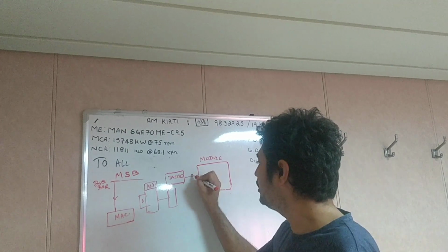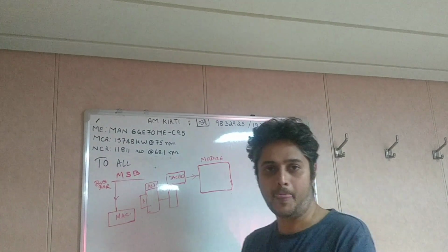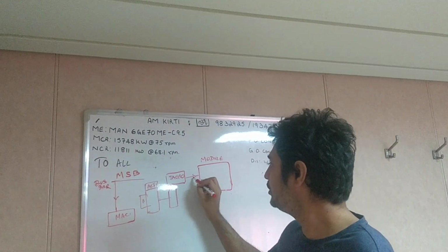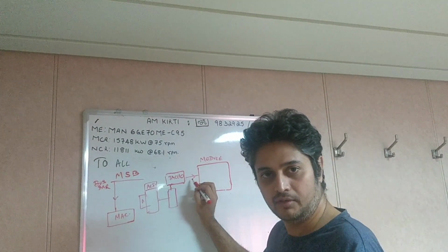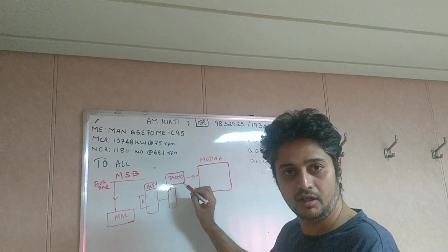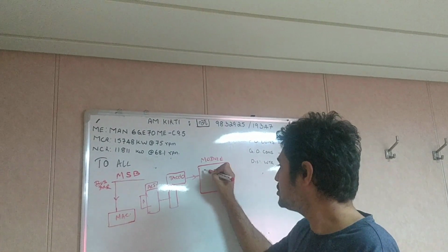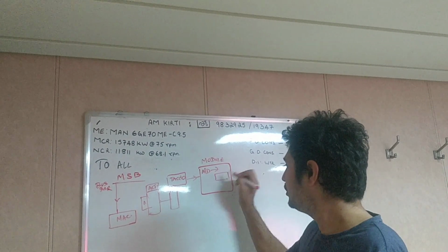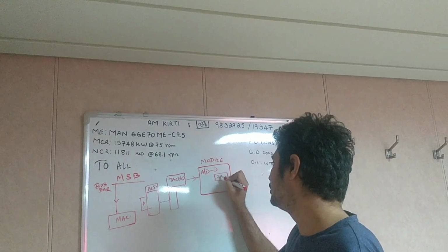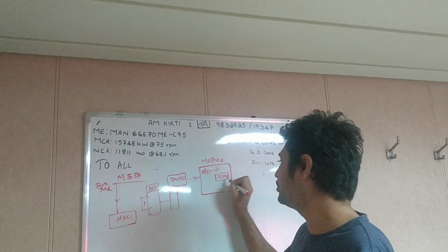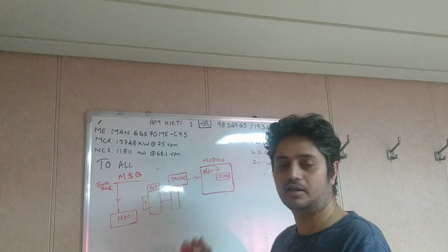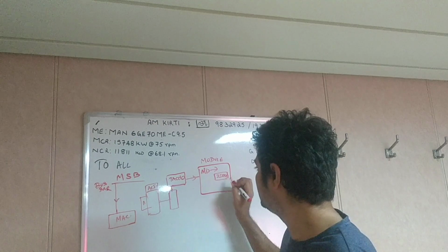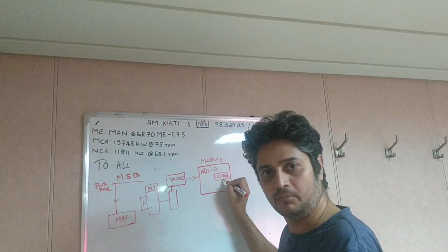Here you will have a display, an RPM display. This comes from the tacho sensor, which gives an analog signal that gets converted by an analog to digital converter and then shows in the module as, suppose, 25,000 or 30,000 RPM, generator turbocharger RPM I am telling. That is for your display, but there is one more thing.